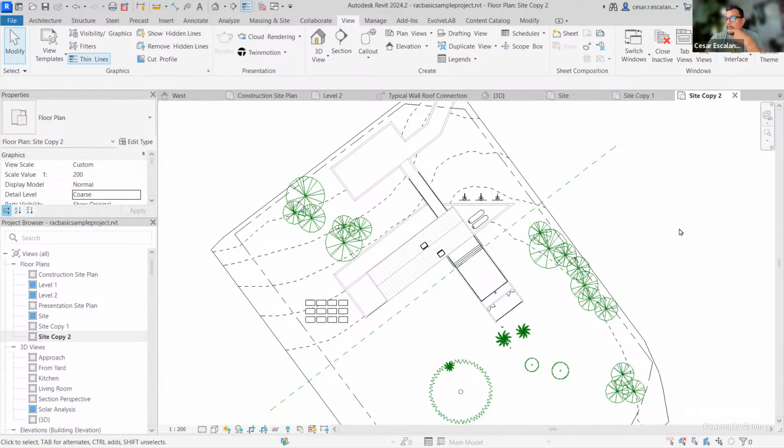And sometimes you can leave these view templates in the Revit template, so other users, if this is a definition you're going to use from project to project, then create the view templates. You can save this project, clean this project, and save it as an RFT, which is a Revit template. And then that's the start of your project, and it will have all the view templates contained there. You don't have to recreate them over and over, project to project. Does that make sense? Okay.